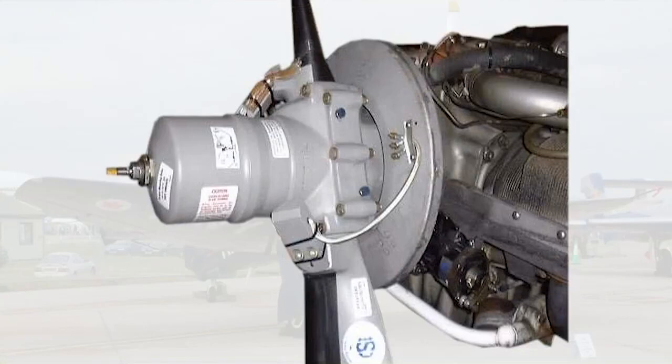Modern aircraft have propellers which are controlled automatically to vary their pitch, the blade angle, so as to maintain a selected RPM. A constant speed variable pitch propeller permits high efficiency to be obtained over a wider range of true airspeeds, giving improved takeoff and climb performance and cruising fuel consumption.